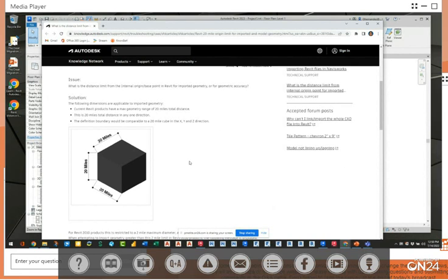Because you can use AutoCAD in Revit, what I want to leave you guys with is this. Be sure to clean up your CAD files. Don't just bring in CAD files willy-nilly. You might have a node hanging out there on the moon, and you're trying to bring it into your Revit project, and it's going to crash everything. So clean everything up, W-block all your CAD stuff, flatten it out, purge them, audit them, and then use those CAD files in your Revit projects.